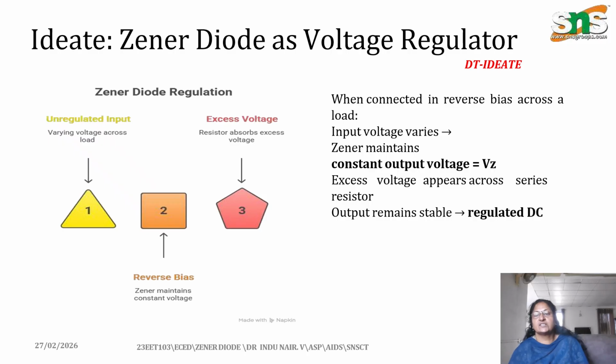Typical applications. Voltage regulation, providing a stable voltage for sensitive components. Example: in a voltage regulation circuit, the Zener diode is reverse biased across the load. Overvoltage protection: connected in parallel, they clip voltage spikes and protect components from transients. Example: in an overvoltage protection circuit, the Zener diode is connected in parallel with the component. Voltage reference: used in circuits requiring a precise reference signal. Clipping and waveform shaping: clipping parts of a signal waveform.